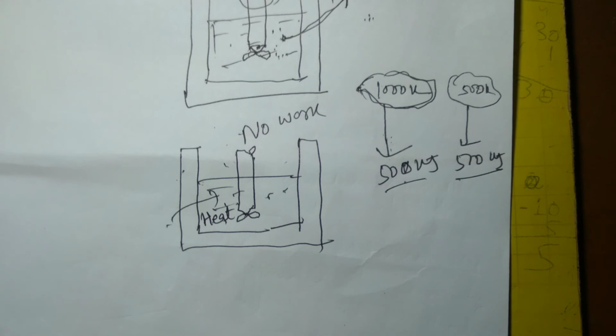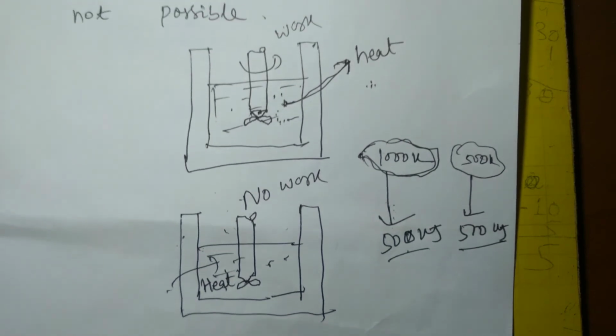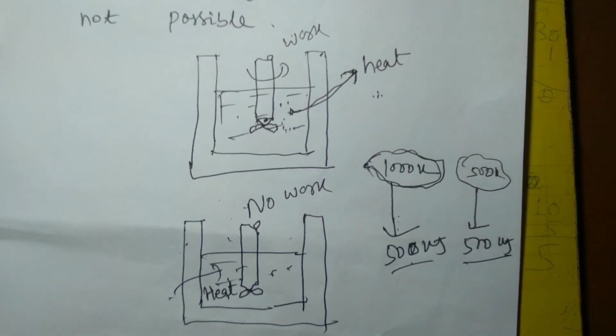So these are the important features of second law of thermodynamics. First is it tells about the feasibility of processes. It can tell whether the process is feasible or not, and we conclude that a process can only occur if and only if it satisfies both first law and second law. Only by satisfying first law alone a process cannot occur, because it has to satisfy both first law and second law. Second thing it does is it segregates energy into two types, low grade and high grade energy, and it affirms the principle that heat is a low grade energy and the complete and continuous conversion of heat into work is not that easy, not that direct, and for which we need certain kind of devices.